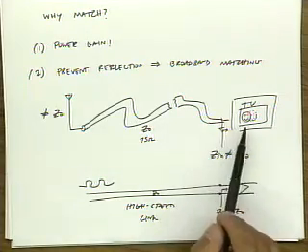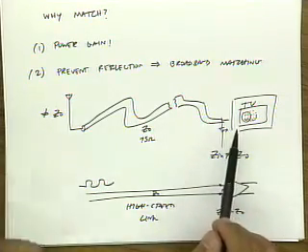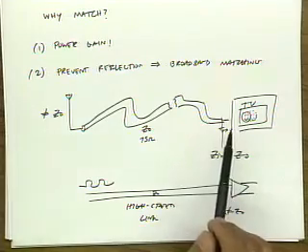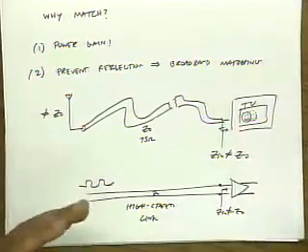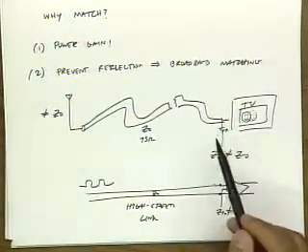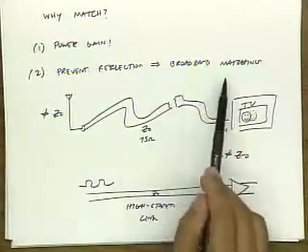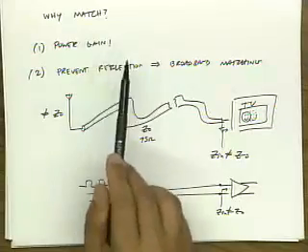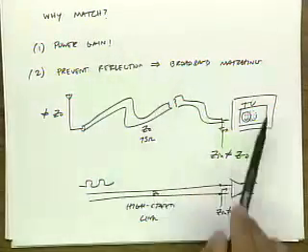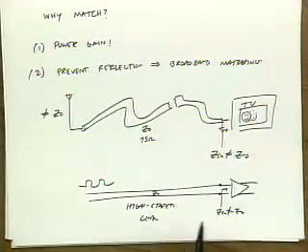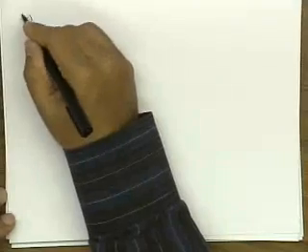Whereas for the television signal, if we're just watching one channel, we could stand a narrowband match. But if you want all your television channels to look equally good, you want a broadband match. There are cases where we just care about one frequency, like maximizing the gain of a narrowband amplifier, and other cases where we'd like a broadband match. Okay, very good. Any other places where matching may help?